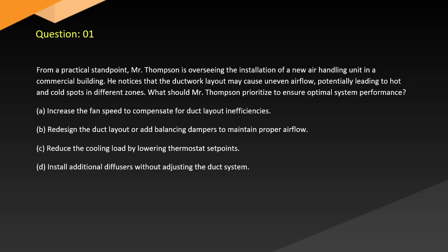A. Increase the fan speed to compensate for duct layout inefficiencies. B. Redesign the duct layout or add balancing dampers to maintain proper airflow. C. Reduce the cooling load by lowering thermostat set points. D. Install additional diffusers without adjusting the duct system.